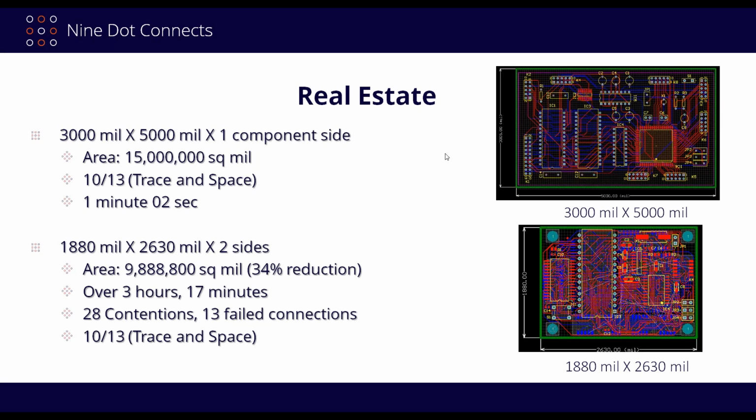And you can see what happened over here. This is pretty much the exact same board, or at least the same type of components, where we started with a 3x5 board. It took a little over a minute to complete. Here's the situation where we left everything the same, the trace and the space requirements, just that we shrunk everything down to 34%. And it took over 3 hours, 17 minutes, and it didn't even finish the route at that point.